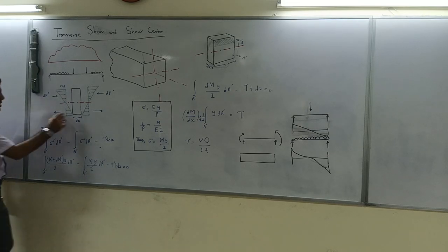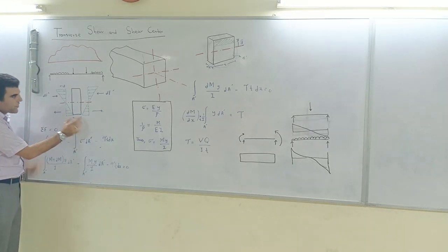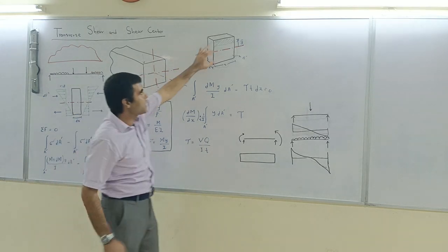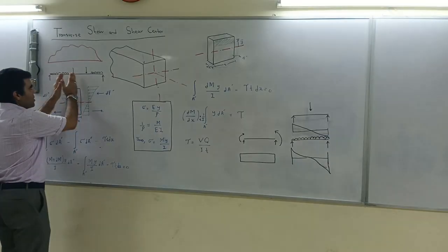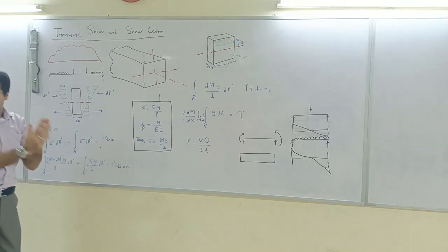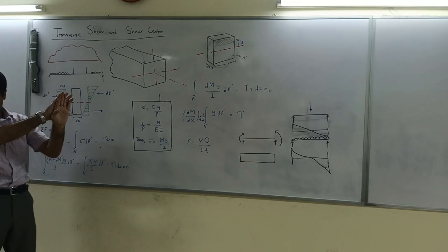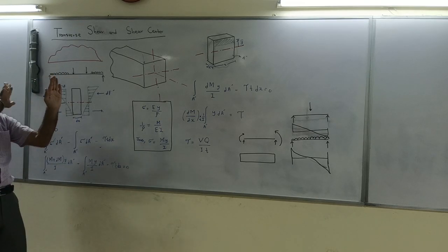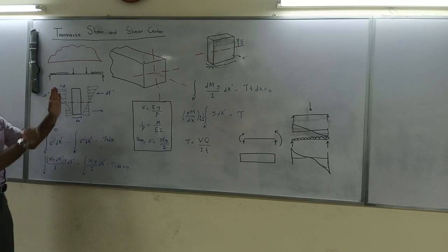This is the stress profile of this region, which has a length dx and area A dash. I've also shown it over here. We take a small region out of this length. This region has some stress on this face and some stress on this face.